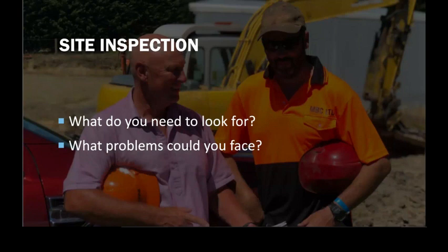Hazards, yep. Trees, roots. So yeah, there's a whole heap of hazards, and we'll be looking into some of those, but there's a whole heap of hazards that you may come across. Some are quite obvious, and others might be hidden, like cables in the ground or other services in the ground, gas pipe in the ground. If you haven't pre-identified where it's likely to be, you could easily run into a lot of bother if you ripped through it with a digger. It could become very dangerous quite quickly.